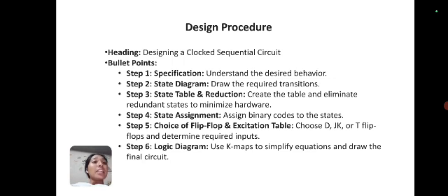Specification: understand the behavior. Step 2, state diagram: draw the required transitions. Step 3, state table and reduction: create the table and eliminate states to minimize hardware. Step 4, state assignment: assign binary codes to the states.